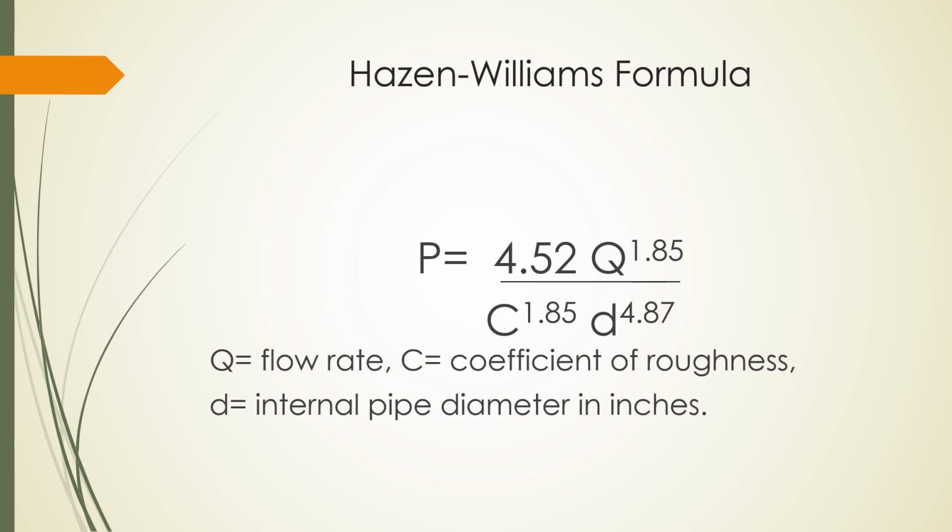This is the Hazen-Williams formula for friction loss, in PSI per foot of pipe. And I just want to emphasize 2 points. One is flow, which is the Q. Just to simplify things, if we square the Q, it has a dramatic impact on the overall friction loss.